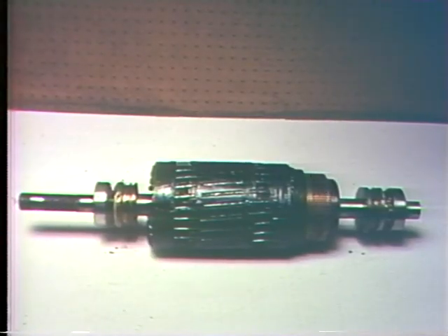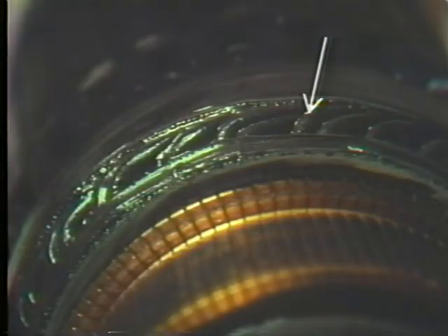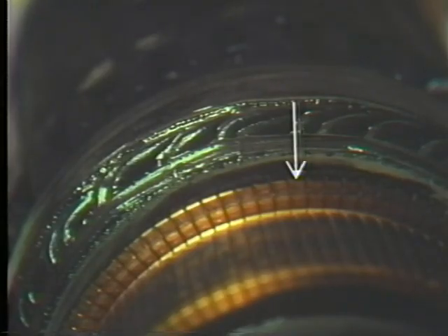The shaft supports the armature and allows it to turn. The core supports and houses the armature windings. These windings are the rotating, current-carrying conductors, and the commutator is the electrical connection that goes from the brushes to the windings. The actual connections to the windings are here on this section of the commutator. These points are called risers.